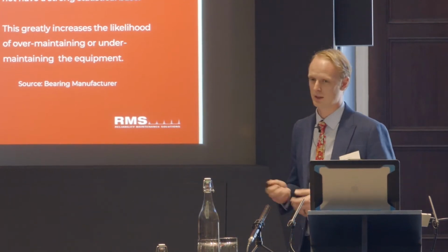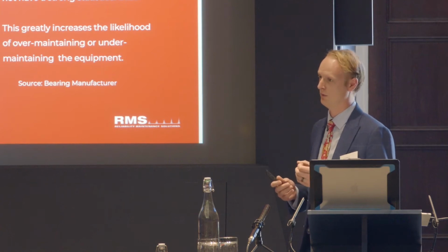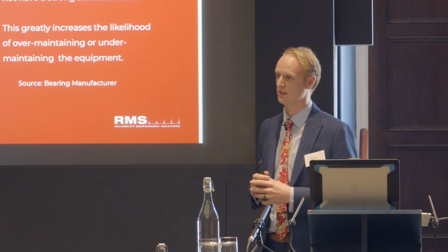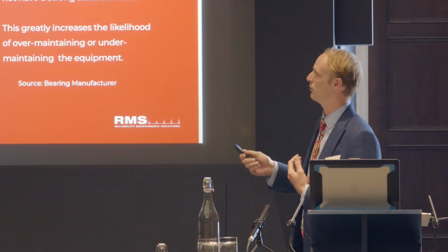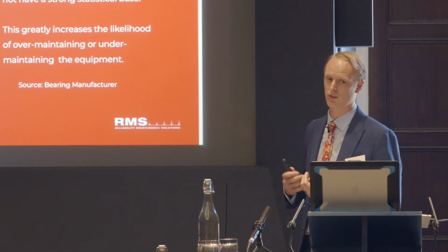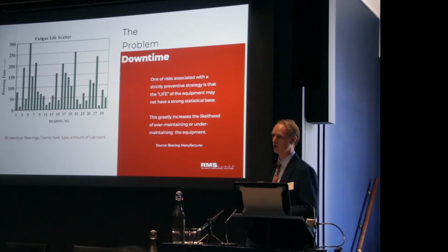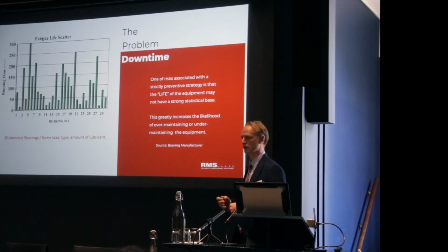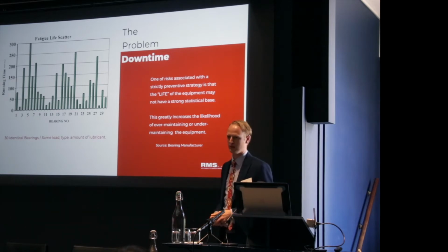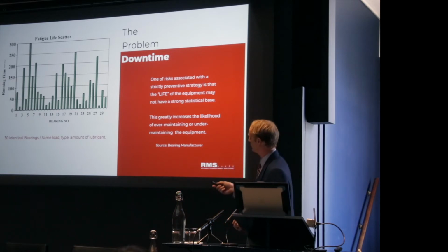If we think about that figure, 80%, that comes from a number of studies that were done later in time, the 70s, 80s and 90s, where 80% keeps coming back for random failures. 80% of all failures are random. So how do you plan for random? If your maintenance strategy is that you're going to change it at this date, but you've got a random time in between there.